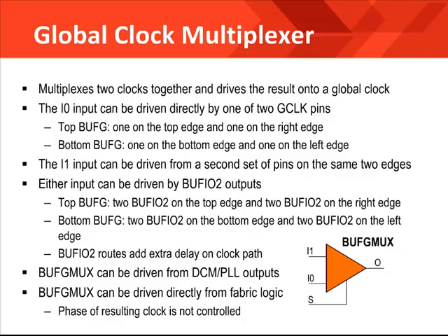What all this means is that knowing how the various possible inputs can connect to the BUFG mux may be helpful if you are distributing a large number of clocks. But frankly, I think it is easiest just to build the clocking structures into your design and then let the tools decide how to group clocking resources to the BUFG muxes. More information on the BUFIO2 cell is given in the I/O clock resources lesson of this module. Likewise, if you're still curious about all the possible connections to the inputs of the BUFG muxes, please refer to the user guide.